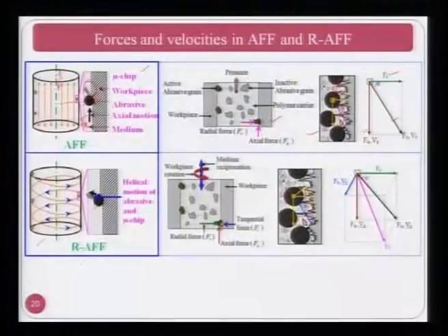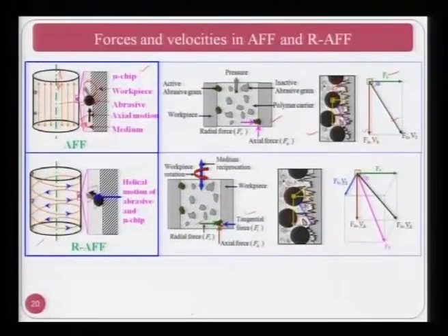In the same way, you can see here the abrasive particle and material being removed in the form of a microchip. Now in this particular case, the radial force is acting due to the elastic behavior of the medium. Then there is a tangential component Ft, which is due to the rotary motion of the workpiece with respect to the abrasive particle, or vice versa. The axial force I have already explained. So if you see the last figure, there is the radial force acting, there is a tangential force acting over the workpiece surface, and here is the axial force.